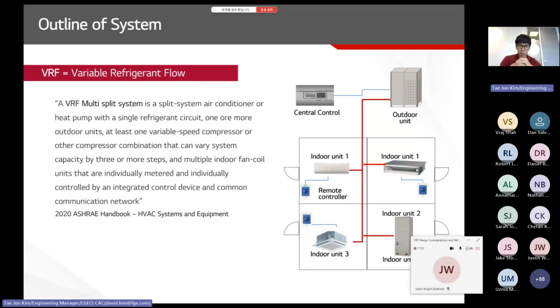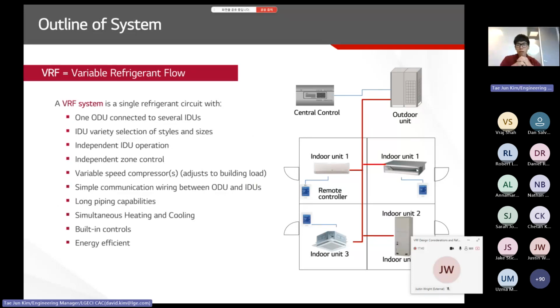If you use the VRF system, it's going to be the perfect application to meet the current electrification that is happening across the country, right? And if you look into the VRF system components, it is very simple. Many of the VRF manufacturers have their controls built into their system, and so it does not require any additional control system in order to operate the system other than just the communication wiring between the outdoor and indoor. And so basically, if you think of it, just connecting the indoor unit to the outdoor unit with the refrigerant pipe with the communication wiring will operate the system. It's as simple as that, right?